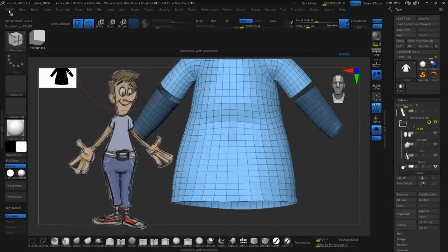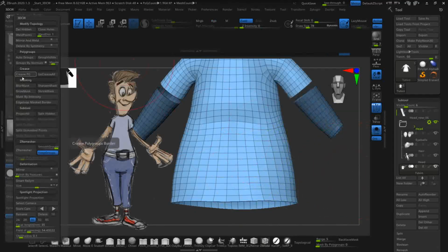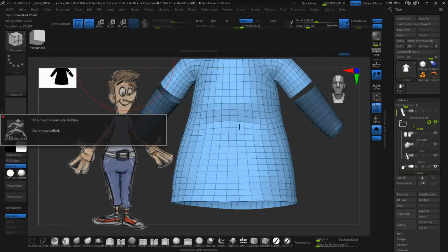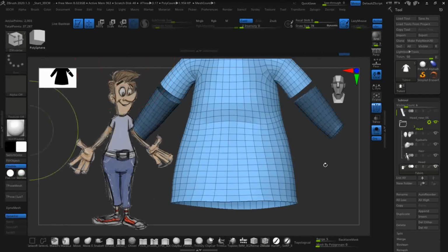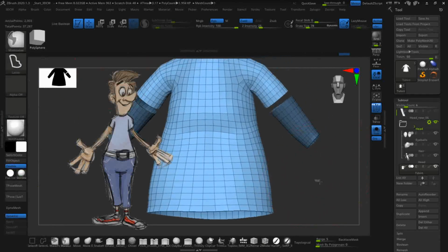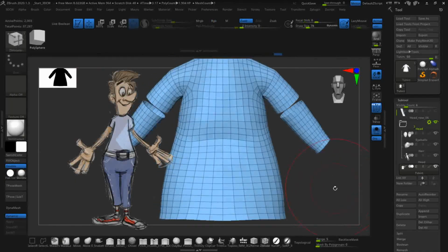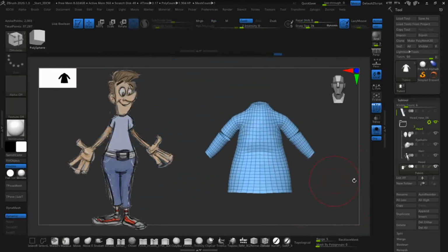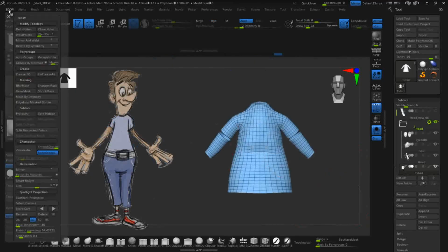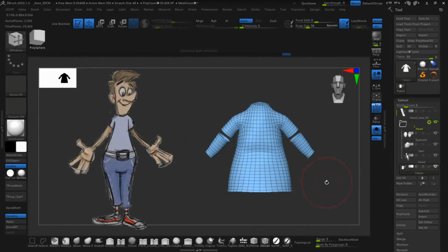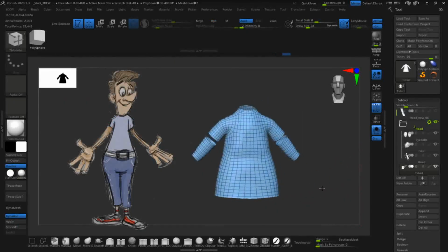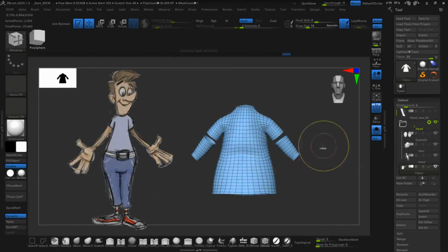And then also in the 3D Character Workshop menu, if you say split unmasked points, it's going to give us the T-shirt. Actually, first thing we want to do is, everything else that's hidden right now we want to get rid of because we don't need it. So if we go delete hidden, that should just be the T-shirt currently, which is fine.